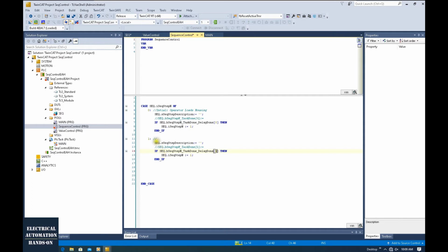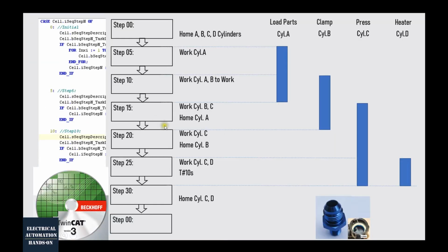After the condition is reached here, to allow the logic to move to the next step, we will move to the number 2. If you want to jump to another step, you can type in the step you want to jump to. So this is step 1. But most of the time, for my style, I will not use the next step from number 1. Personally, I prefer to use the next step at 5.